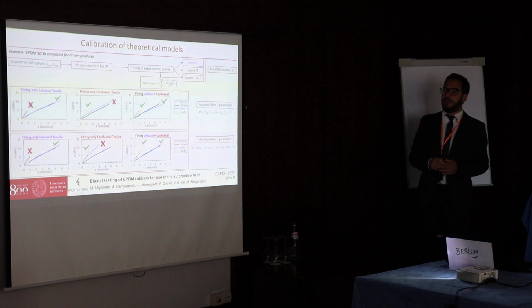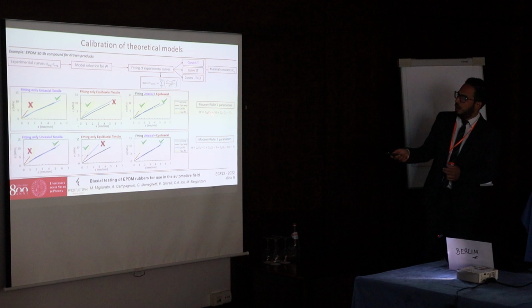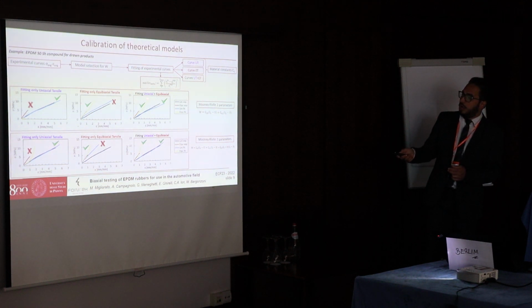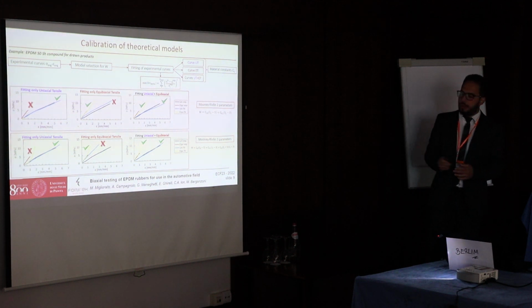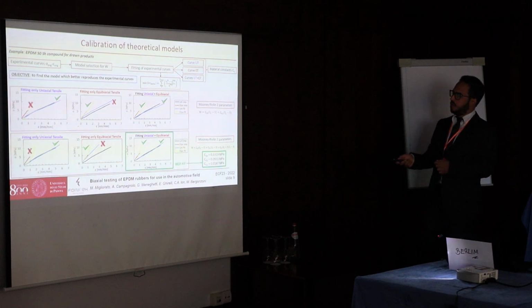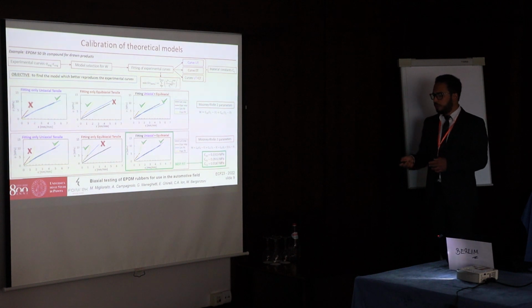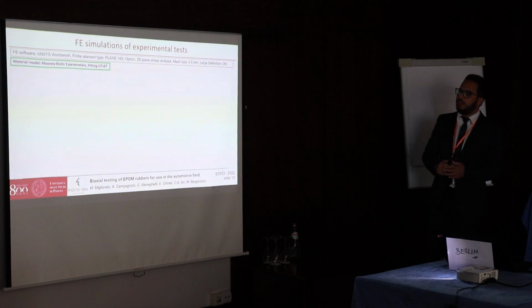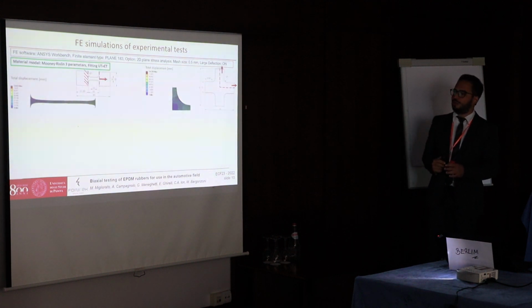So, by taking advantage of a combined fitting available in ANSYS Workbench, we have fitted both models on both experimental results obtained under uniaxial and equibiaxial loading, obtaining a good agreement. And it can be observed that the model which best fits the experimental results is that provided by Mooney-Rivlin with 3 parameters. So using this model, we have performed a finite element simulation of the uniaxial and equibiaxial tensile test. I'm close to finishing.